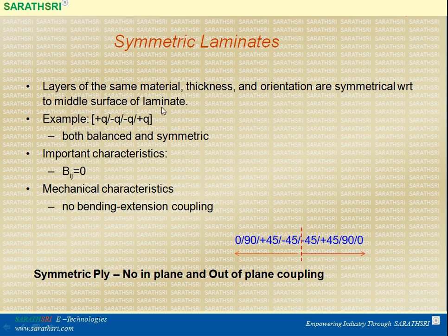The layers have the same material and thickness at different locations, having the same theta. The advantage of a symmetric laminate is that the coupling matrix vanishes. So there is no in-plane and out-of-plane coupling in the case of a symmetric ply.